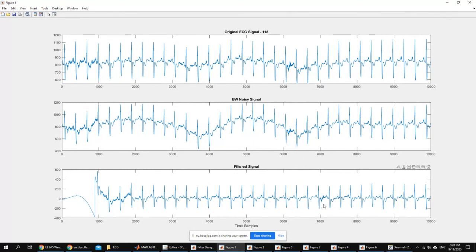And you'll find that it's delayed by basically half the length of the filter. Okay, meaning that it's 900 points delayed from the actual signal. So we'd like to take care of this delay actually. If we wanted to get the difference, to make sure that we remove the artifact correctly, we have to take care of this difference. We don't want to have a delay in this filter.